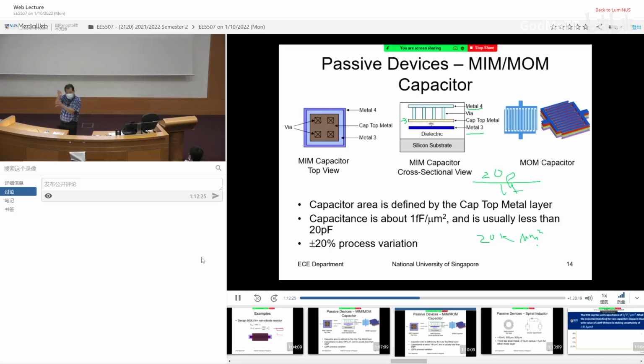If I can get two resistors match very well, down to 1%, my gain accuracy down to 1%. I design gain of 20 dB, it will be 20 dB. Very little variation. So that is the reason why even if the component value is not accurate, you can still get very good, accurate circuit performance. Okay?